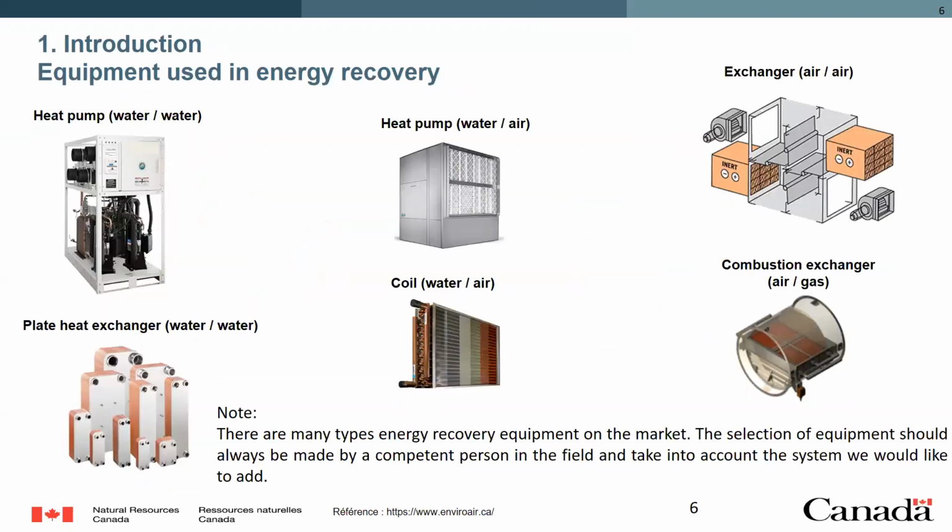Okay. So what are the systems, what is the equipment used for the heat transfer? As you can see in this slide, we have plate heat exchangers or coils or combustion exchangers or regular exchangers. It will depend on what you're exchanging, what kind of fluid you're exchanging, either air or water. And there's additional equipment that can be used for energy recovery. In this case, the heat pumps that use the same principle of the refrigeration machines that can allow to transfer heat from one medium to